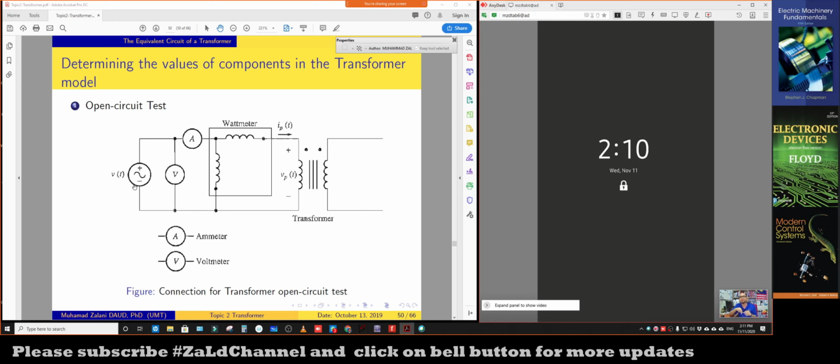They use the power analyzer to measure the voltage, current, and also power of the transformer, and I am talking about a high voltage transformer. They use that instrument to measure voltage, current, and power based on the open circuit test or short circuit test.